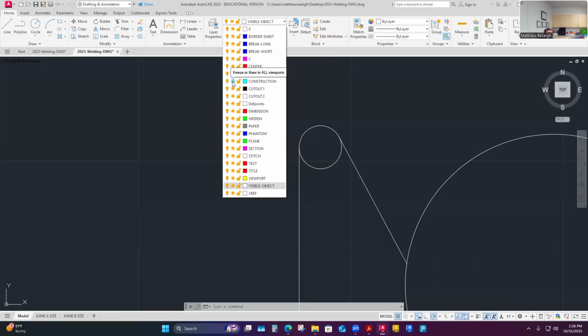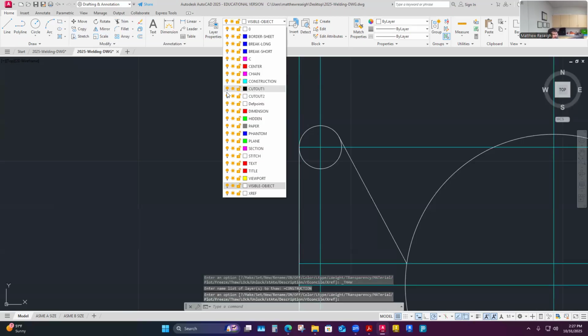But when you get a drawing that has 100 layers, or if you reference somebody else's drawing of a house or something, and they'll have 100 layers, those can bog down how fast your computer can process all of those points and coordinates, just point to point data. So if you freeze it, it frees the computer up so it doesn't have to track that data. And you're not moving that stuff anyway, so you can freeze it and let it stop computing it. We don't use it a lot. Our drawing is super simple, so it's not even anything I need to worry about. I just want to tell you what it is.